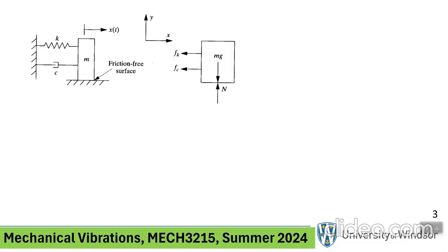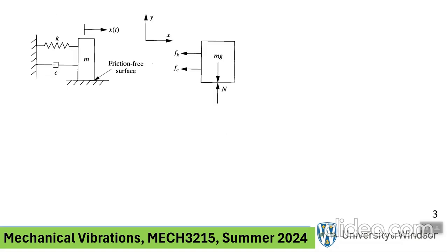Okay. Now, we have a mass and spring, and let me see if I can have the drawing here. Mass and spring, as shown on the left-hand side, and now we add a damper, and the damper is of a very special type. What that means is that we are assuming viscous damping, in other words, the velocity of the mass m describes the force by the damper resisting the motion of the object.